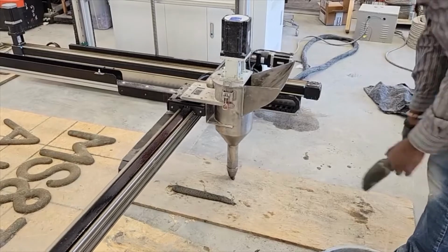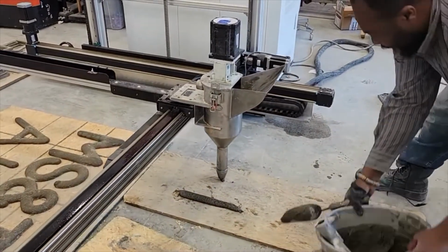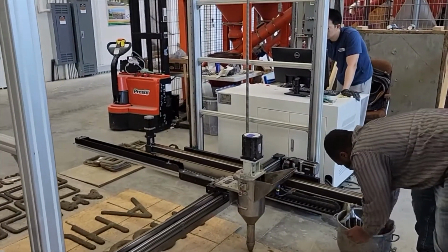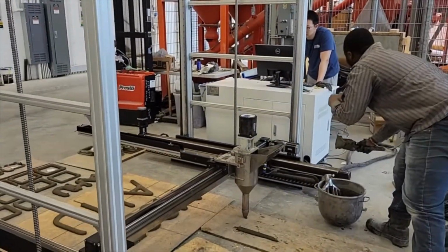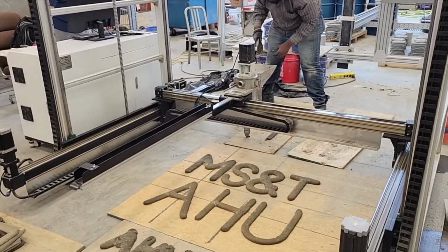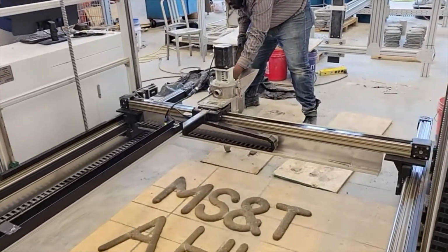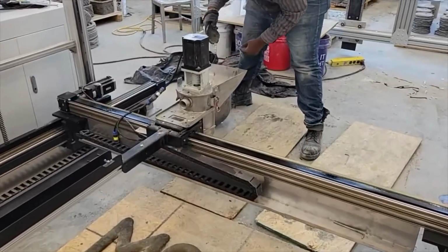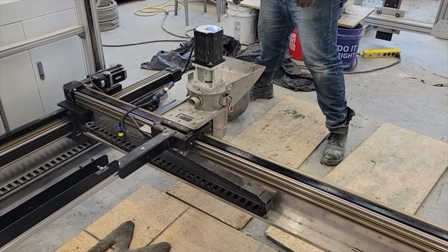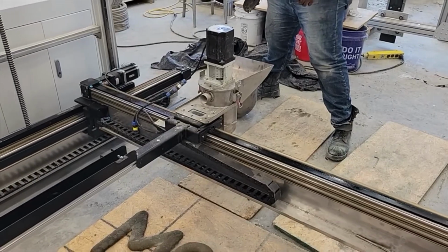In our experiment, an extruder barrel almost exploded when a very high force was applied to the fiber-reinforced concrete mixture to push it out of the nozzle. When aggregate or fiber accumulate near the nozzle and block the outlet, it's almost impossible to push the material through. Even if the material is pushed through the nozzle, it may not be homogeneous.